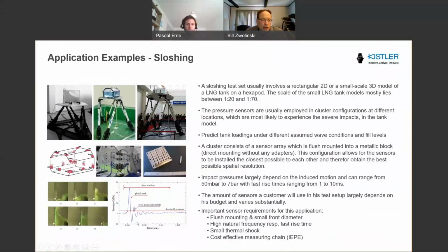because when you have air and water, they're not necessarily at the same temperature, and even a few degree temperature difference could result in substantial errors. So having a measurement like the 601C that I mentioned, which has a special diaphragm that's optimized for thermal transient response, really helps in taking such measurements.